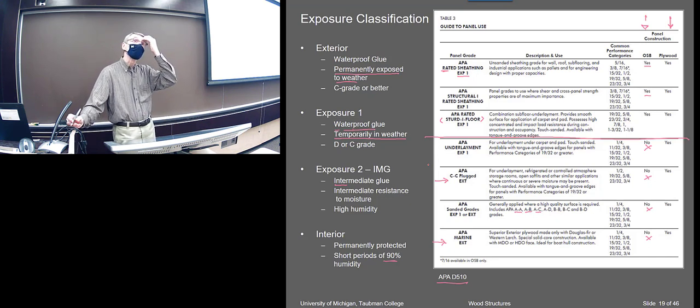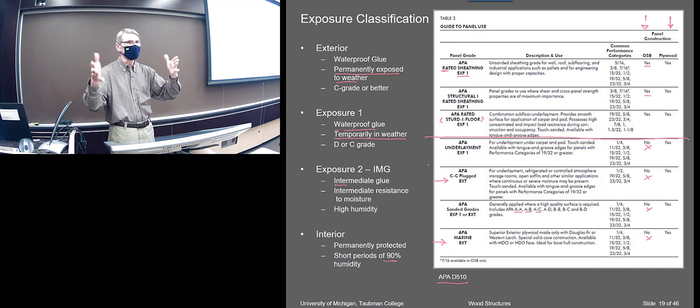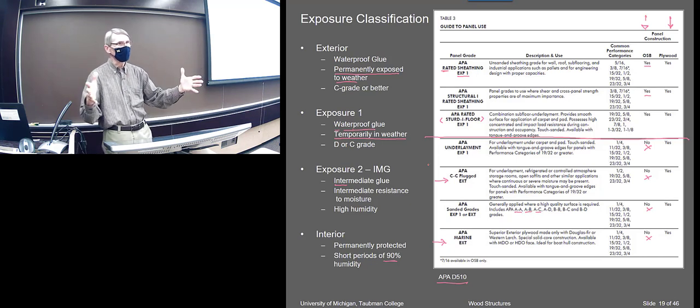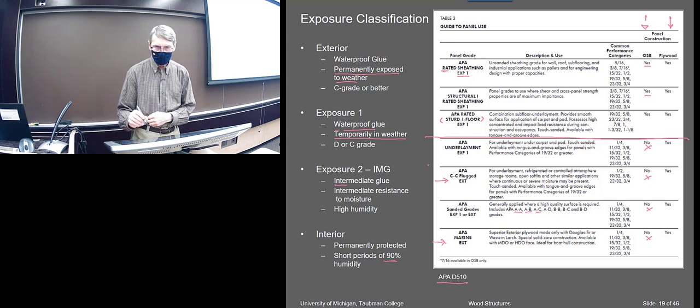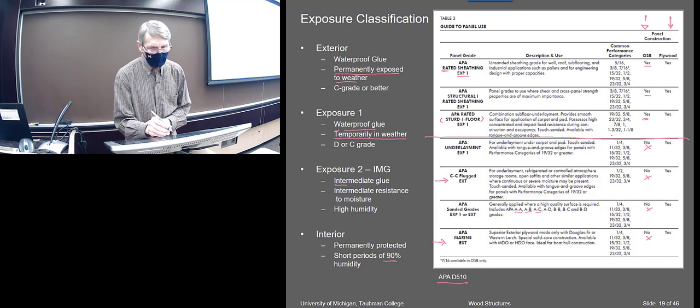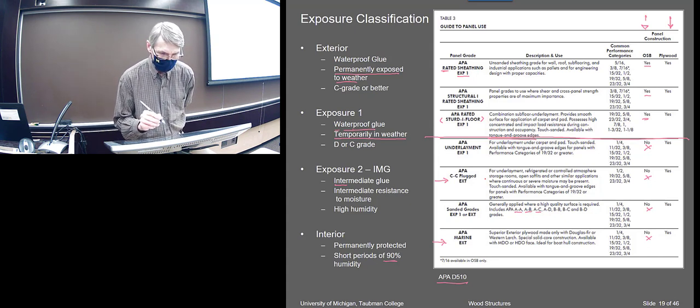It gets up to L over 480 stiffness, and it uses I-joists, and the rim board has to be made out of LVL, I think. It's a whole system, and you have to buy into the package. This plywood would go with that. Plywood or OSB apparently would go with that package. And it has to be tongue and groove and all that stuff to give it that sturdy floor, to make sure it gets that stiffness level.